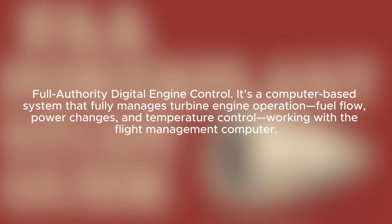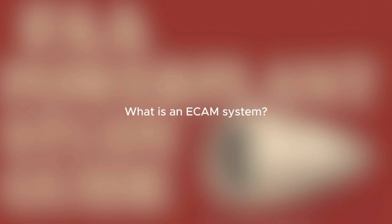What does FADEC stand for, and what does it do? Full authority digital engine control. It's a computer-based system that fully manages turbine engine operation, fuel flow, power changes, and temperature control, working with the flight management computer. What is an ECAM system? The electronic centralized aircraft monitor tracks engine and system performance, displays warnings, and can even show checklists during system malfunctions.